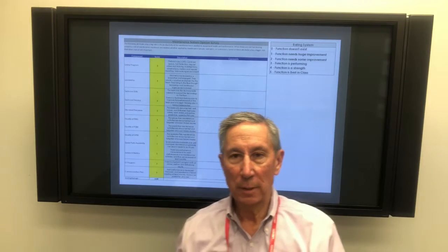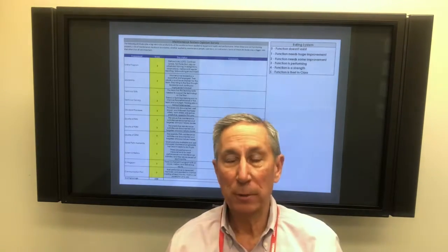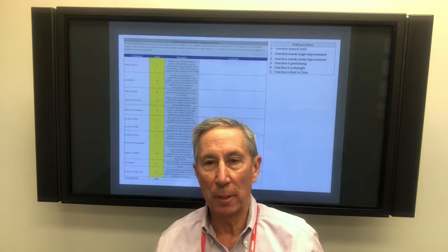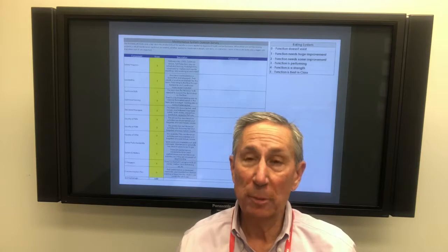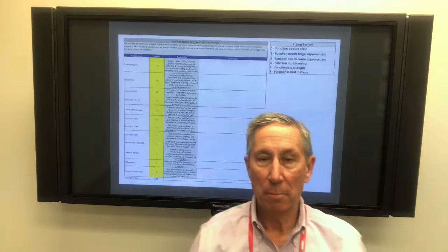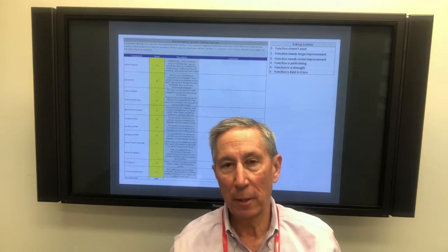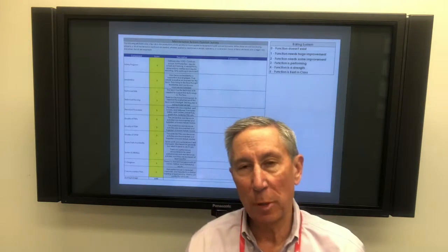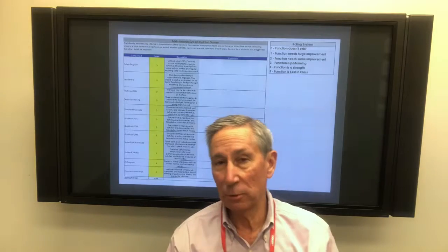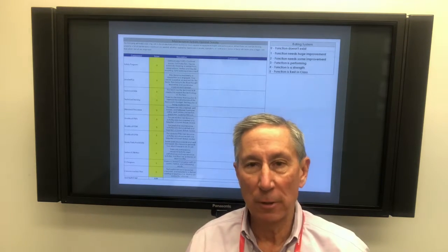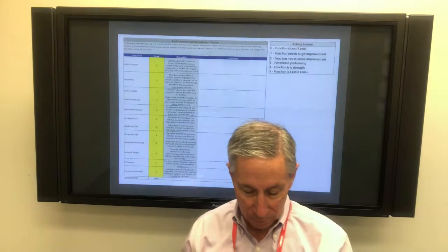The next component is systems and metrics. If we're using a CMMS, are we collecting the data appropriately? Are we creating measurements to show our performance: machine availability, downtime, mean time between failure, mean time to repair, work orders waiting on parts? So systems and metrics is really key. Let's see, do we have all this in place, and ask people for that.